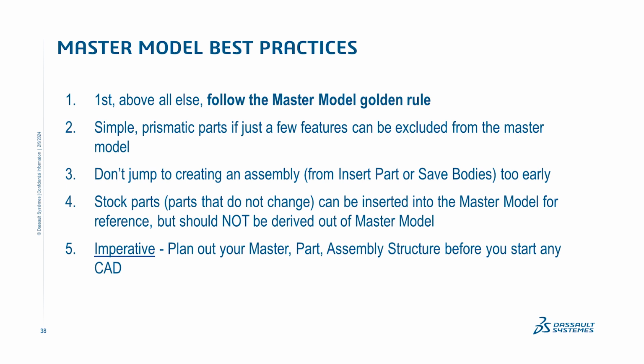Stock parts are very, very useful for inserting into your master model to reference. I do this all the time, and it is a good thing to do because, again, stock parts aren't going to change, so you don't have that danger of external parts updating and breaking your master. What you do want to do, though, is at the end of your tree, delete those stock parts before you do save bodies, just to make it clear that you never want to pass those stock parts through a master and then into your assembly.